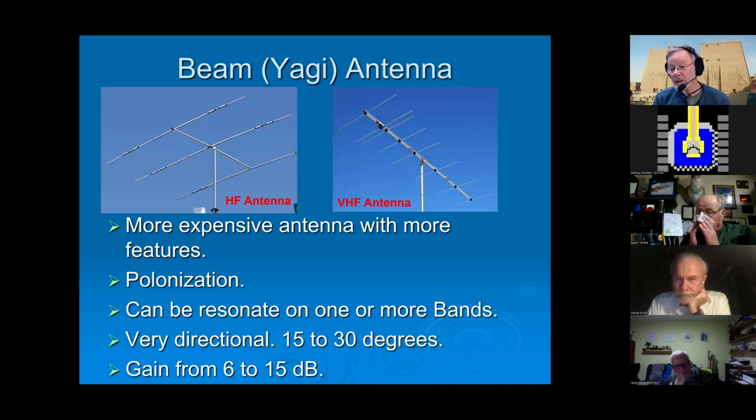It depends on what the ham operator wants to do. If he wants to work a bunch of sideband and get more distance, you'll see that thing in a horizontal configuration like it is. If you just want rag chewing, get into repeaters and talk locally, then that thing will be in a vertical orientation.